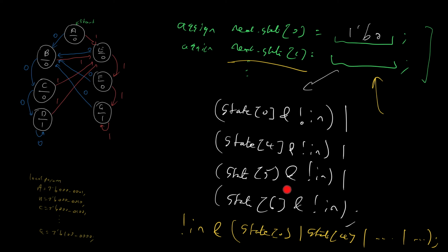You don't have to do this yourself. Quartus will figure this out for itself. You just change the localparam here, and if the rest of your code is correct, Quartus will deduce this for itself. And then when you're using one-hot encoding, you can look again and see how many logic elements are being used and what is Fmax.